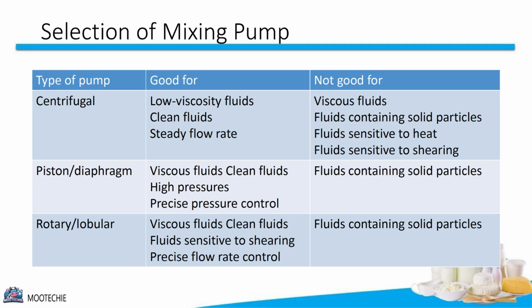Centrifugal pumps are good for low viscosity, clean fluids and steady flow rates, but they are not suitable for viscous fluids, fluids with solids, or shear-sensitive fluids. Piston or diaphragm pumps handle viscous fluids and high pressures well and offer precise control, but they cannot handle fluids with solid particles.